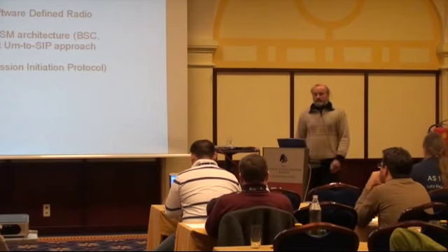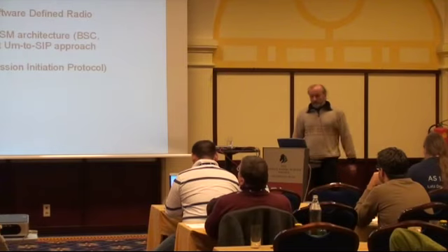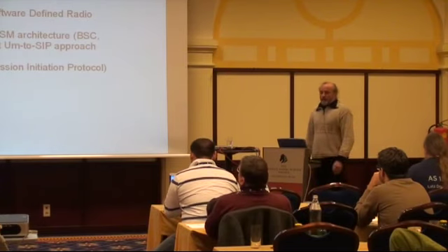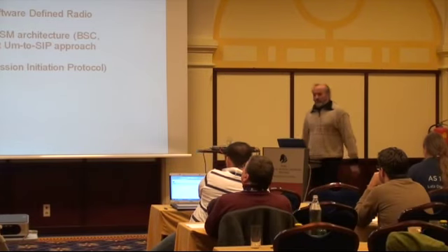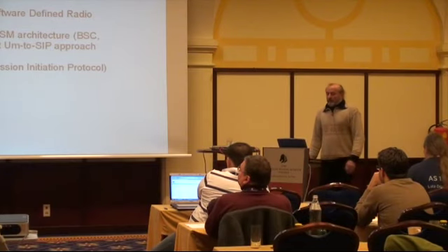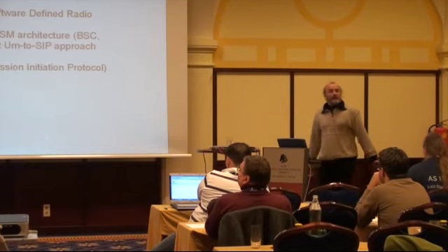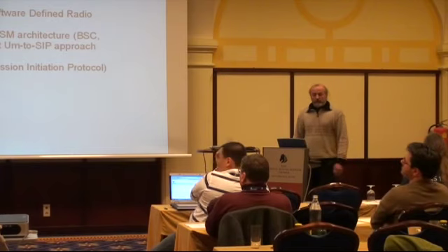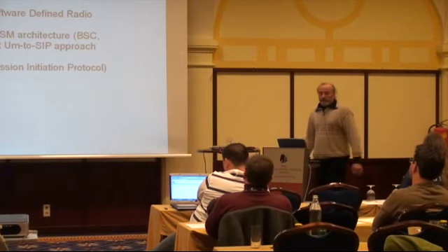It all depends on the radio front ends you plug into the USRP. OpenBTS implements the air interface as a software-defined radio. This means all the signal processing, modulation, demodulation is done in software which runs on the PC. OpenBTS does not directly model this GSM architecture I've shown in the picture before. It uses a direct RAM to SIP approach. SIP is basically you get voice over IP afterwards, and it uses Asterisk, an open source phone switch, to make the calls into the network.